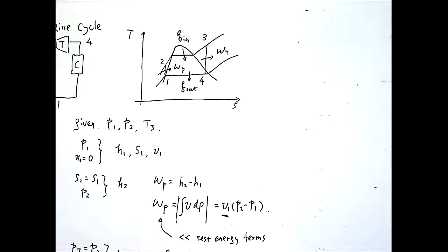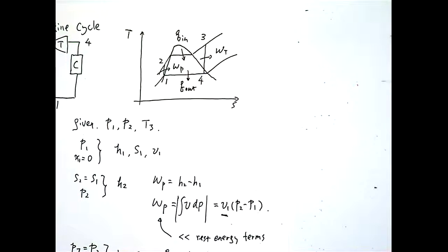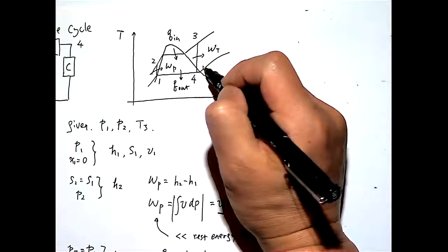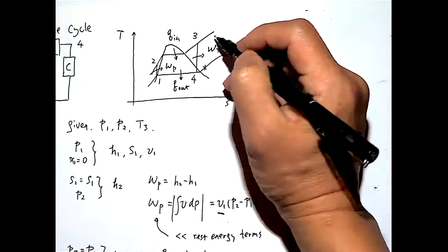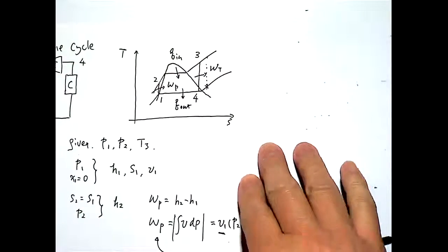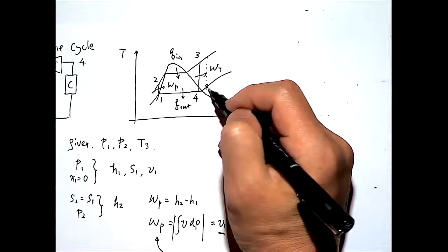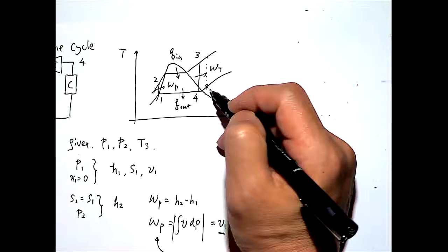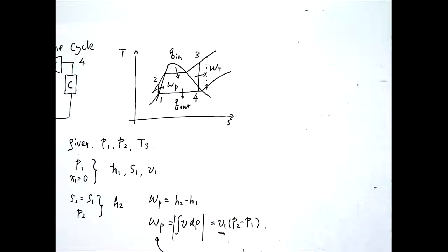The conditions are still known. The entropy is known. Let's say if you end up over there, which corresponds to another process, right? In that case, the pressure is known, the entropy is known, the state is known, right? You just go to a different table to figure out everything.